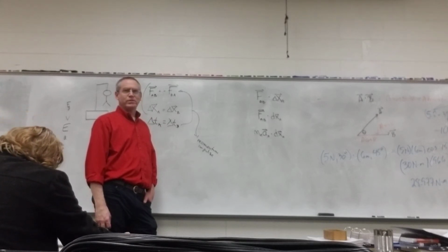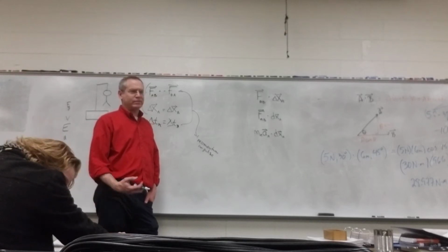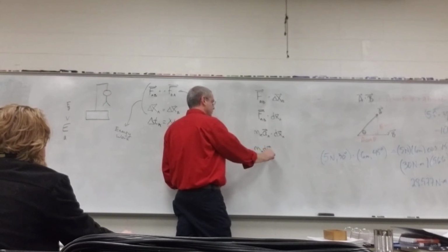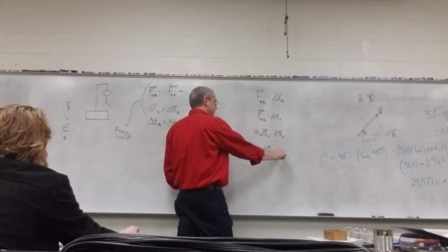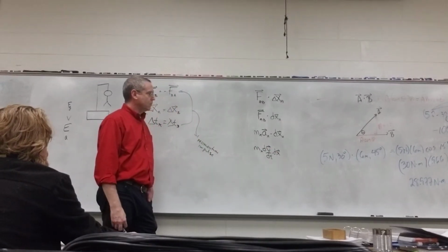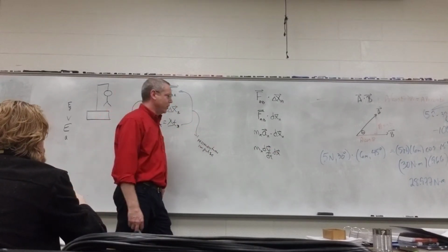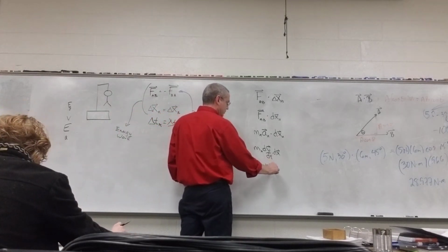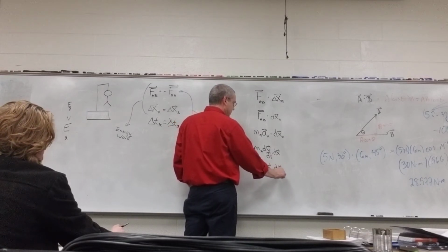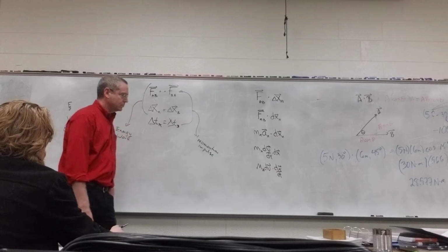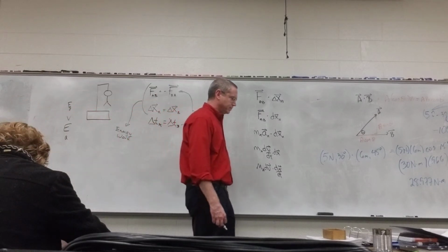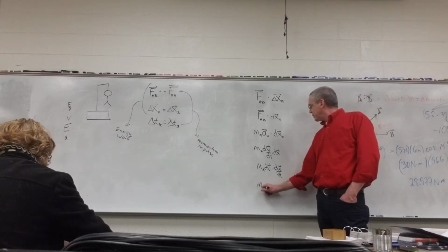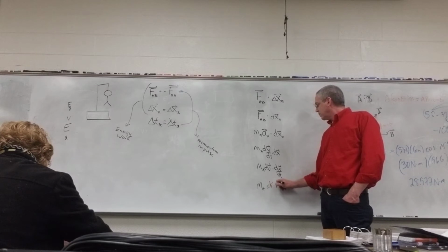Well, the definition of acceleration: change of velocity over change of time, or the calculus version, dv dt. So dv dt times dot dx. I can just take that dt and shift it over, and so make this mass of A dv dot dx dt. And what's dx dt? That is velocity. So this becomes mass of A dv dot v.